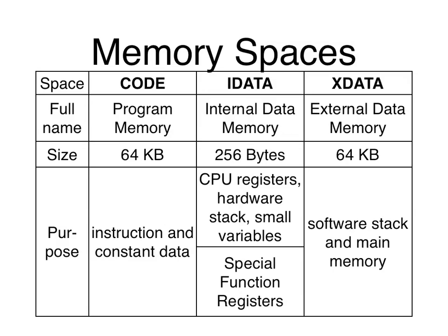Now, to talk about 8051, you first have to understand the memory spaces that the instruction set architecture defines. So there are several spaces, roughly divided into what's called code space, IData for internal data, and XData for external data. So there's at least these three spaces. At least that's how I like to view things.